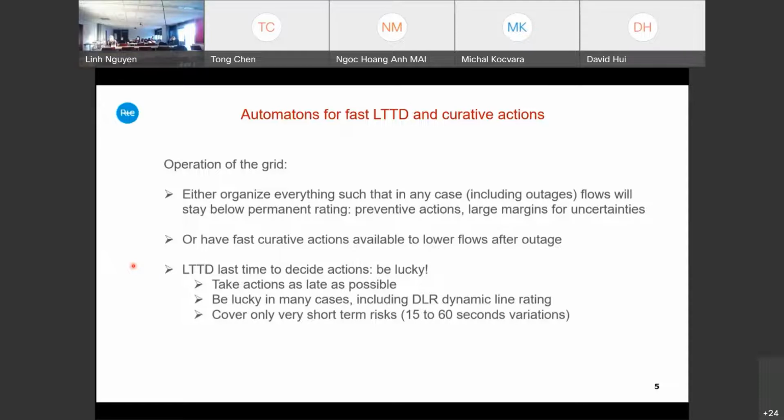You have a bit less wind than expected, or a bit more consumption than expected, or some wind farms are not working for some reason, or the wind is in the right direction and the cooling of the equipment is so good that you can really put 150% of the standard capacity, because the wind is cooling so well.